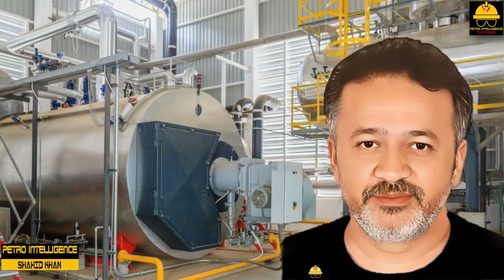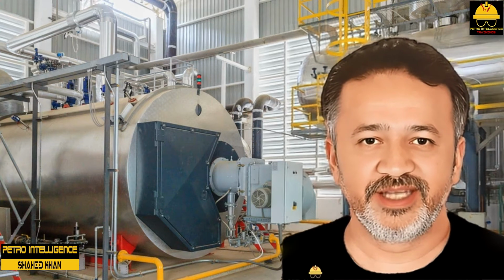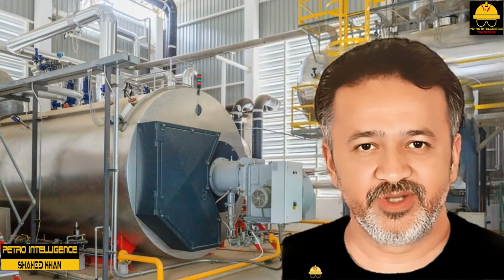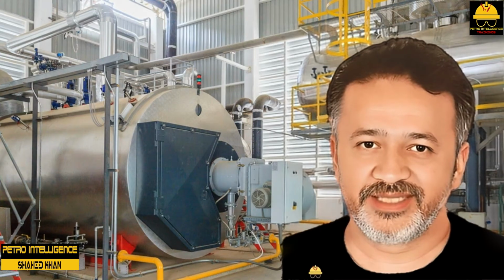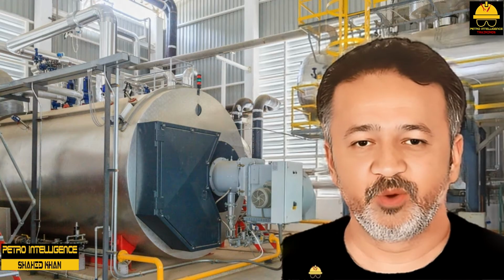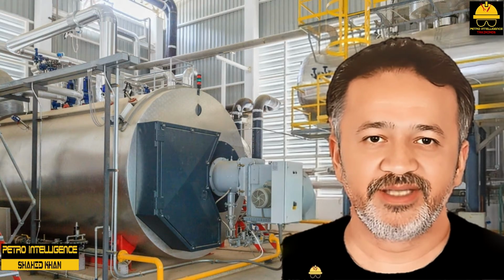Fire tube boilers. A more complicated boiler is the fire tube boiler, which resembles a modified shell and tube heat exchanger. This type of boiler is composed of a shell and a series of tubes designed to transfer heat from the fire tubes into boiler feed water. Combustion gases exit through a chamber similar to an exchanger head and pass safely out of the boiler. The water level in the boiler shell is maintained above the tubes to protect them from overheating.